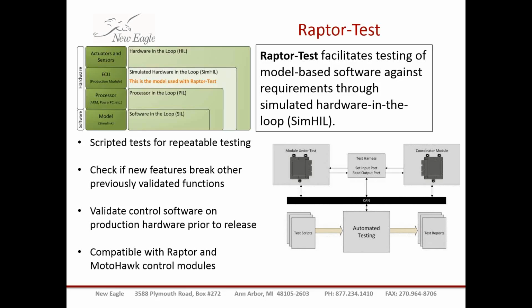And that's especially useful because if you're working with a prototype vehicle or expensive hardware that's cost lots of money to develop, you might not necessarily want to test your prototype software on this expensive hardware. So what you can do is create test scripts to simulate the rest of the hardware in your system, and that allows you to validate the control software that you're developing.